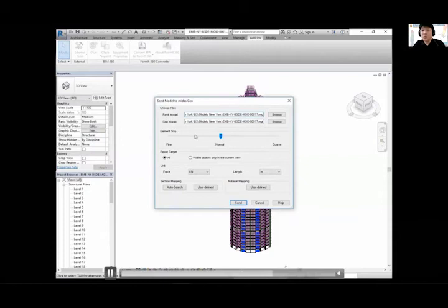So you just choose the name you are going to save it with, and here you can choose the element size for slabs and walls that you are exporting. Also, you can choose the unit and just click send, and then it will save the MGT file, which can be imported in Midas Gen. Let's go back to the presentation.